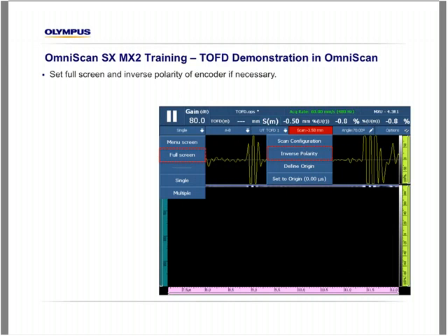Okay, at this point, the OmniScan is ready for the inspection. We're going to save the file, press and hold over this area of the OmniScan, and name the setup OPS file something logical. Anytime you see a little star next to the OPS name here, it's an indication that something has changed prior to saving the file. So save the file at this point prior to the inspections.